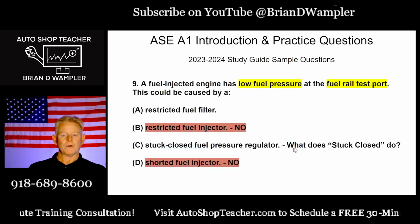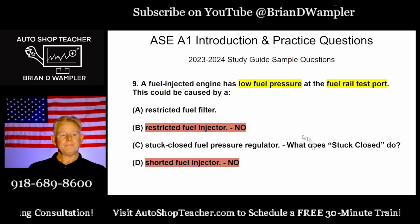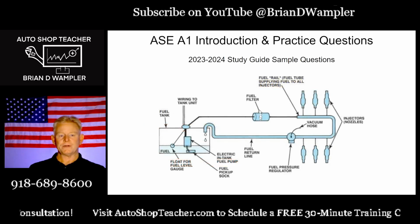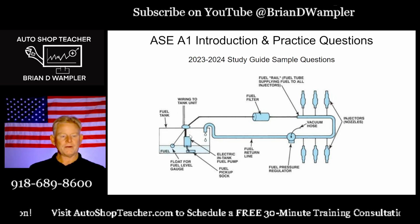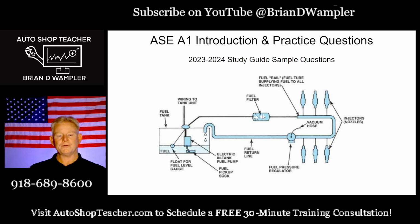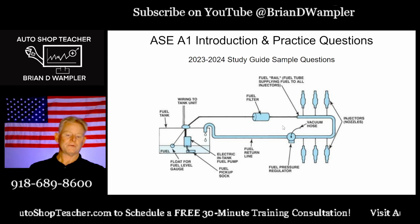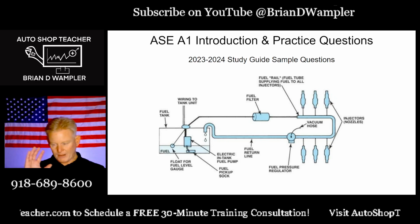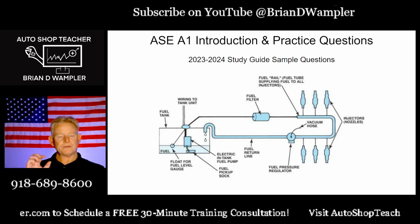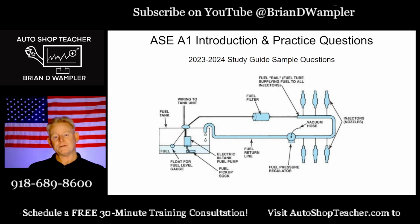Okay? So our only option in this case would be A. If the fuel filter was restricted, then the fuel pump is down here and it's just going like crazy trying to get fuel to the fuel injectors, but it's trying to push it through a fuel filter. I know that was kind of a winded answer on this one, but remember this is the A1 practice test and we're dealing with a fuel system here.